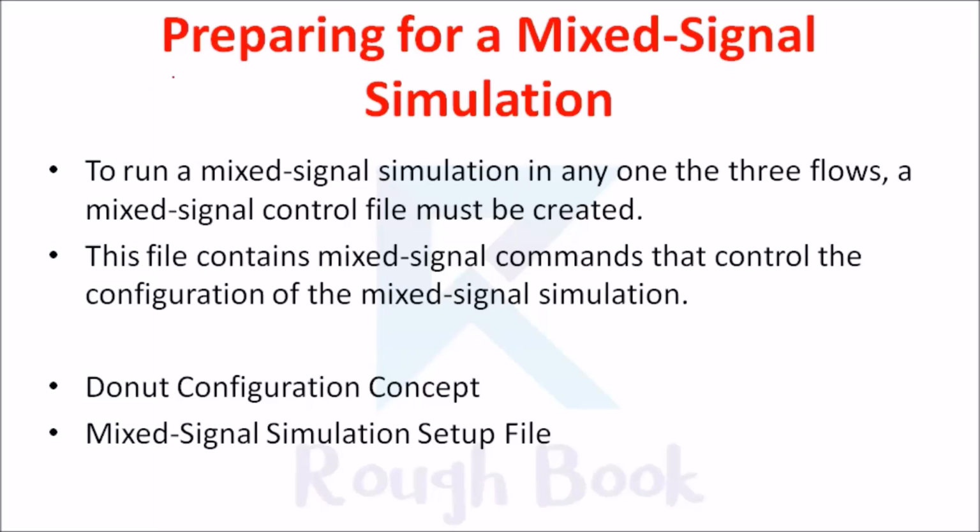In this video, let us see about preparing for the mixed signal simulation. To run a mixed signal simulation in any one of the three flows, that is Verilog Spice, VHDL Verilog Spice, Verilog AMS Spice, a mixed signal control file must be created. So, what does this control file do? It contains mixed signal commands that control the configuration of the mixed signal simulation.